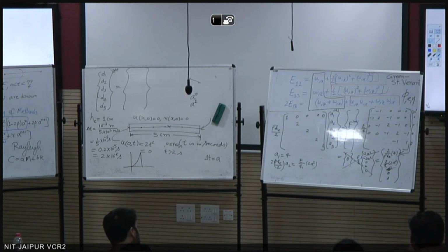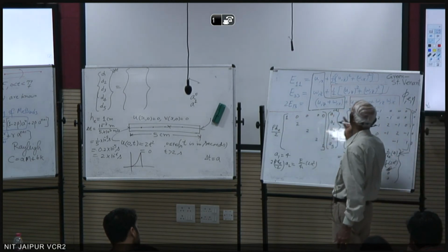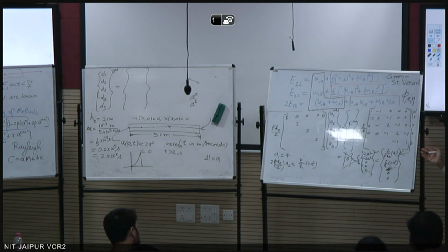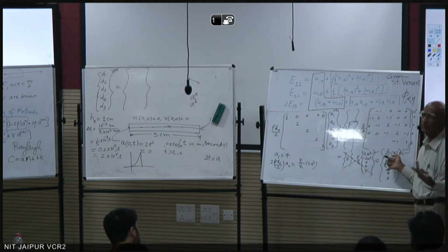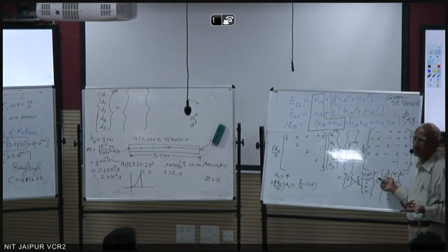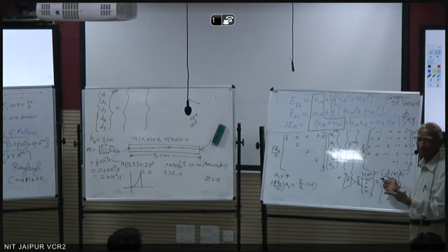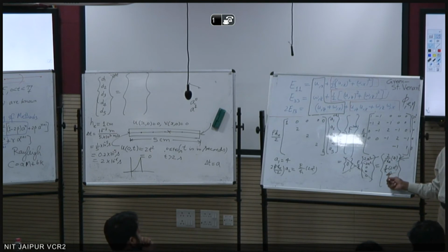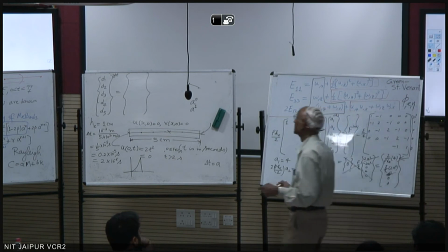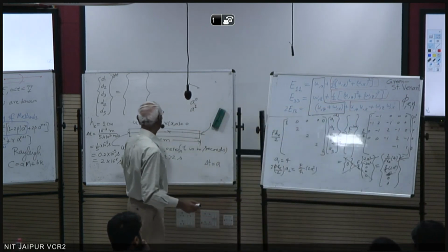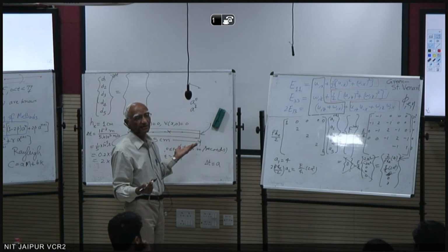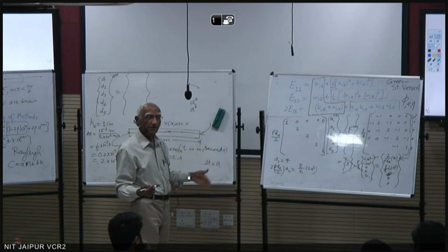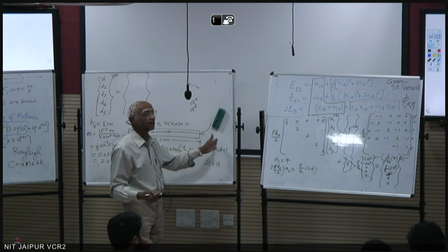So we are not using Lagrange multiplier because this equation is trivial. This equation says mass times acceleration equals the force. And if you want acceleration to be 4, you put here mass times 4, mass of the first node times 4. So what will happen is you will get a non-zero entry here, possibly a non-zero entry here. So when you find the D's, they will be not zeros at 1, 2, 3, 4, 5 nodes maybe. When you go to the next time step, you will get all D's not 0.